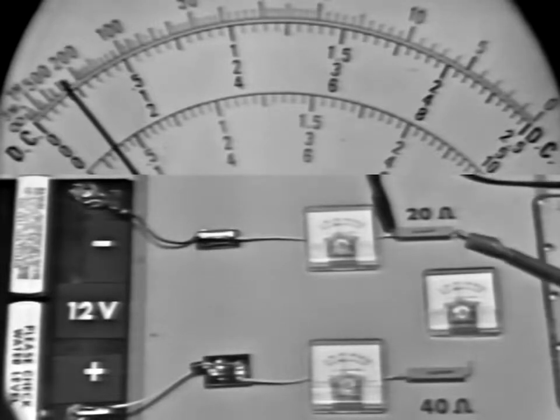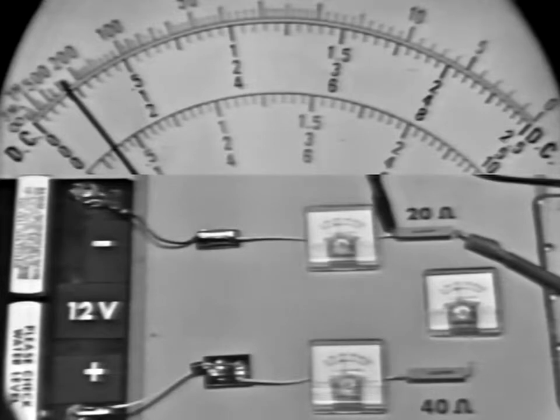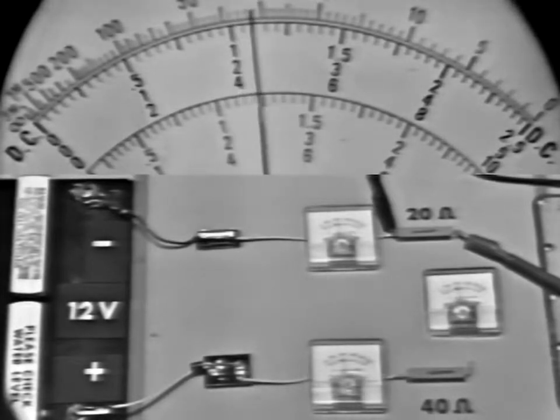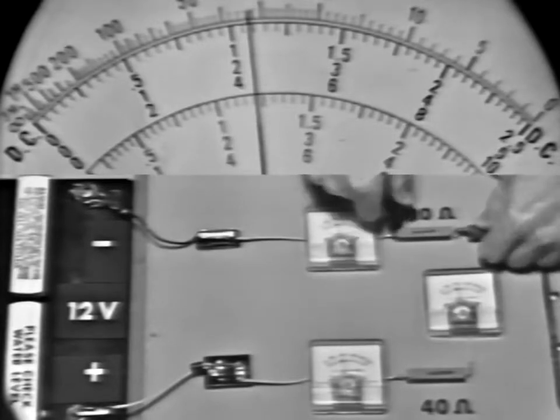here. You see we get a deflection, but it's small. It's very difficult to read on the 50-volt range. However, it is less than 10 volts, so it's safe for us to decrease the range to 10. Okay, you see that we get a much more accurate reading. Now, on the 10-volt range, we use the bottom numbers of the DC scale. You see that we get a reading of, well, it's about 4.3 volts. 4.3 volts across this resistor.